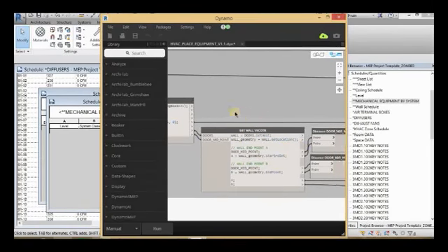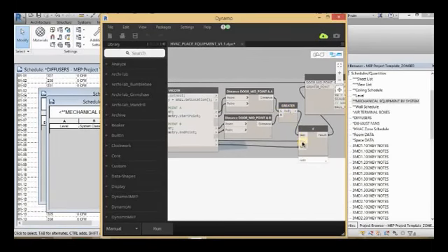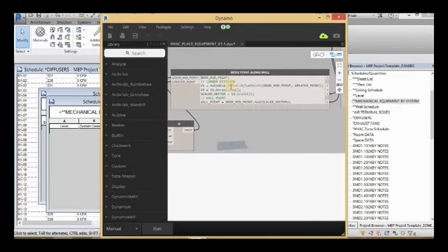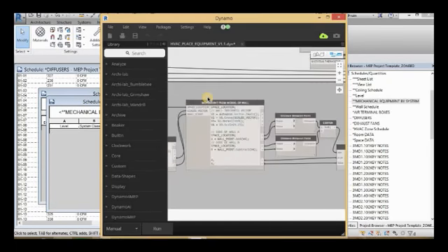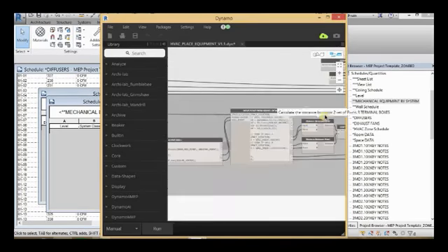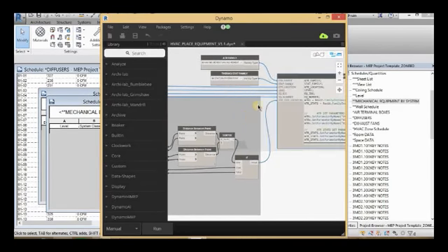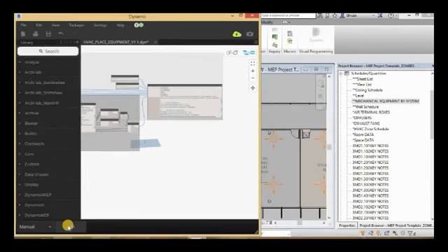So here we go. Same thing. So vector points, and here we're doing the distance thing, seeing which one's greater. The one that's greater, we're getting that point. So now we make a vector from those 2 points. We scale it to be about 3 feet, and then we move it down that vector. So here's the normal thing again with the cross product. Again, cross product gives you that normal to the wall with Z. And we will pull the one again, that's shortest. And so let's give this a run.